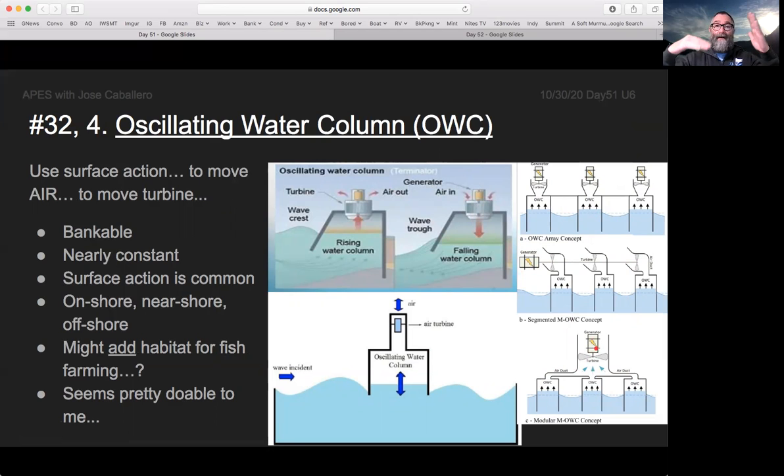You can have valves that close off on 2 sides of a turbine. So the outgoing air spins the turbine this way. And then when you need to suck air in, this flap opens and the incoming air keeps the turbine spinning. So you can have exiting air and entering air on the same turbine. Push the air out and it spins. Suck the air in and it spins.